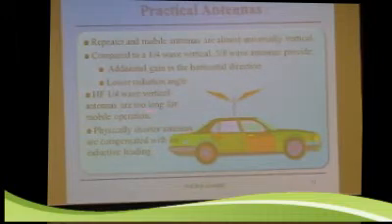Also, if you're operating HF, quarter wave antennas are too long for mobile operation. Again, that would be for 80 meters, a 65-foot whip sticking off the back of your car, which the policemen, and you'd have trouble going under overpasses and all kinds of stuff. So they do physically shorten the antenna by using some inductive loading, and you don't get something for nothing. That antenna is less efficient than a full-size antenna. But if you are on a car, you can't have a full-size antenna, so you use what you can use.